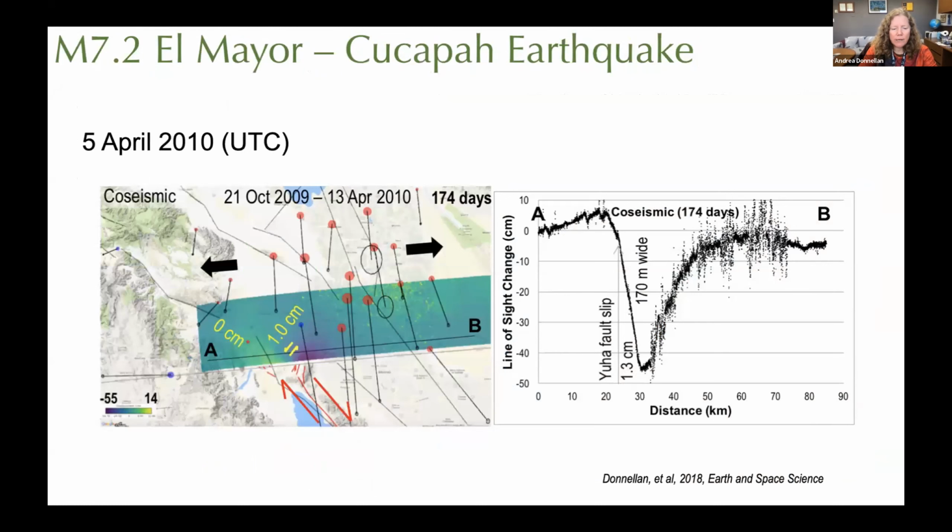This is the radar interferogram. The swath is about 15 kilometers wide and about 90 kilometers long. We have a set of them that go all the way up through the Los Angeles basin, but I wanted to show the south one. Purple is away from the aircraft. The aircraft is flying left, or to the west. Purple is away from the aircraft. Yellow is towards. So we have this right lateral motion.